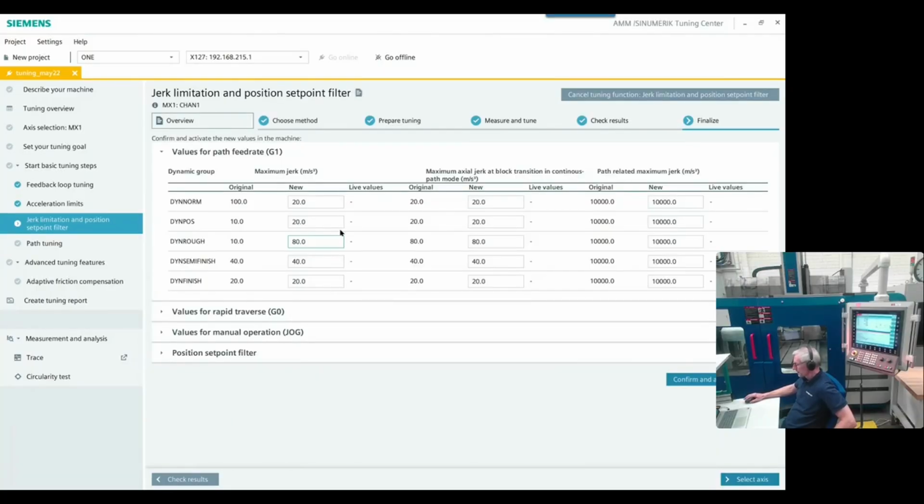So now here we are talking. This could be used as a part of the advanced surface calibration, really, when we're trying to set this up and we don't know where to start. This certainly gives us an idea. Mm-hmm. Yeah, especially if you get the feedback from the customer that he feels that roughing is still too slow, then you can have a look at that jerk number here.